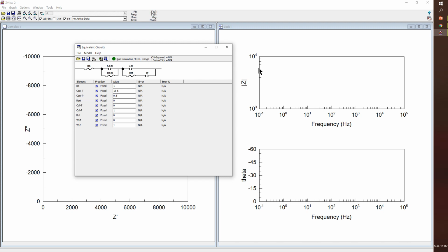You know, when P equals 1, I could say this is the capacitor. However, typically we cannot obtain ideal capacitance. So the farther away from 1, it means non-ideality is increased. I mean, again, when P is going away from 1, it means your capacitance is going to more non-ideality. So here 0.8. Usually P value would be between 0.5 and 1.0. More practically, P value is around 0.9.